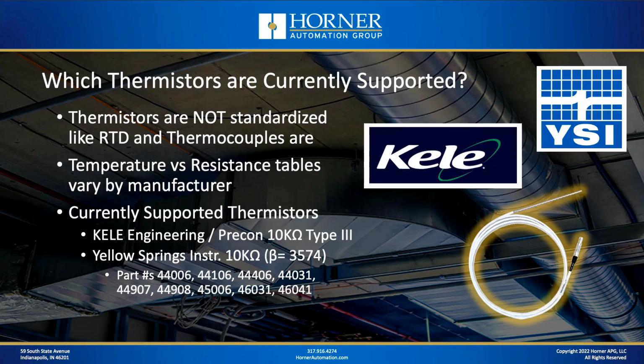Their Precon 10K ohm Type 3 thermistors, we support those. And from Yellow Springs Instruments, otherwise known as YSI, we've got some 10K thermistors that are also supported, and you can see those part numbers listed on the chart. So if you're looking to use thermistors with the Horner products, you need to choose from these particular thermistors.